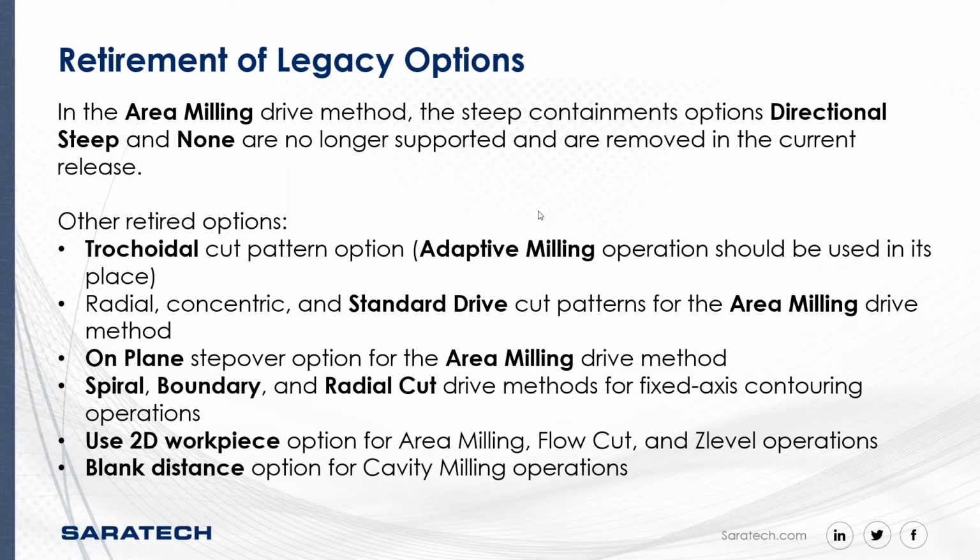In my opinion, cavity milling is starting to get more into the legacy side of things. So radial, concentric, and standard drive cut patterns for area milling are no longer supported. So you'll no longer see them.